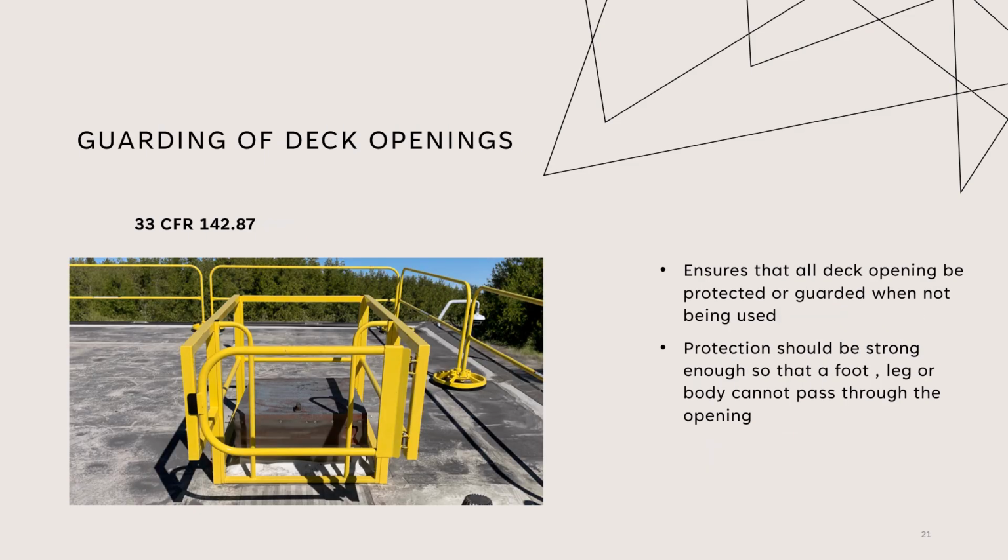33 CFR 142.87 covers guarding of deck openings. It ensures that all deck openings be protected or guarded when not being used. The protection should be strong enough so that a foot, a leg, or a body cannot pass through the opening.